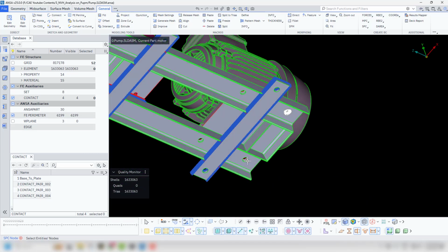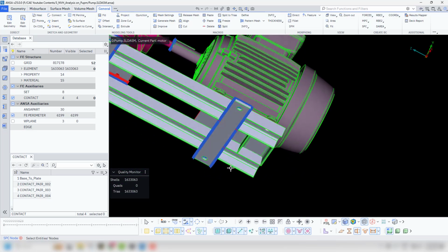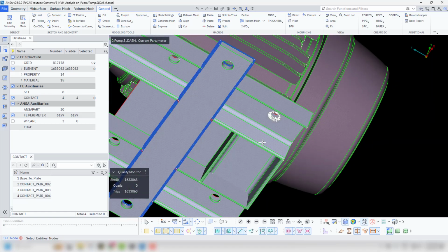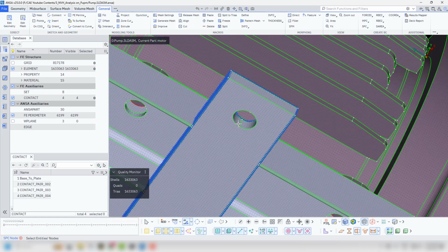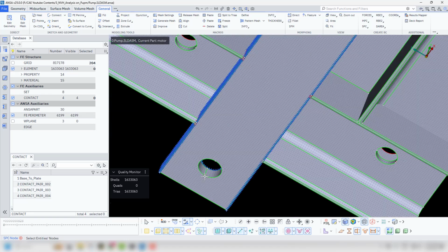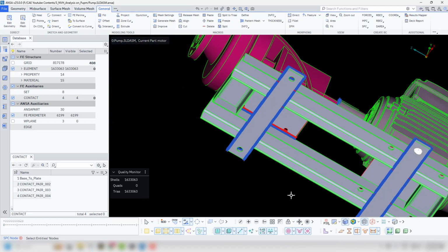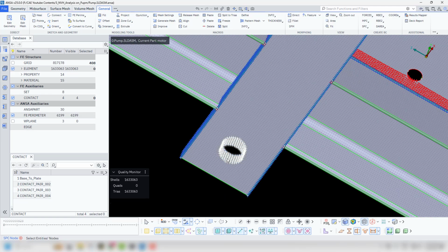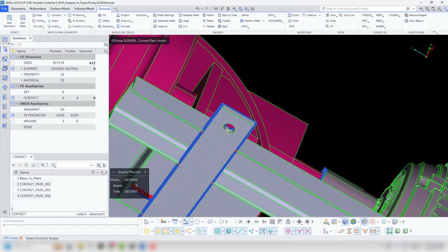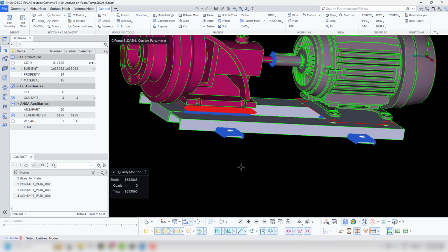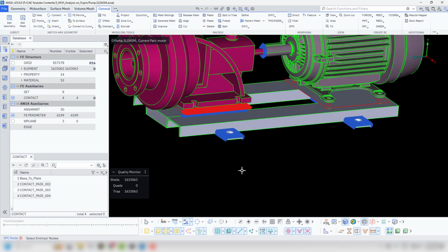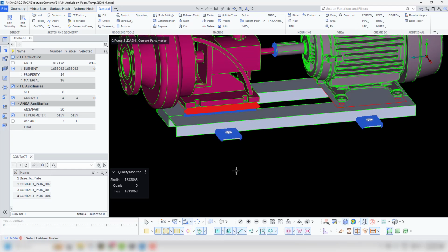So you can define it. You could see this is the bottom supporting plate, the resting region. So here you can just select the regions where you're gonna bolt it and fix on the ground, right? So this should be completely fixed. All the 6 degrees of freedom should be 0 for me. So you could see once you click on OK, you have the constraint.